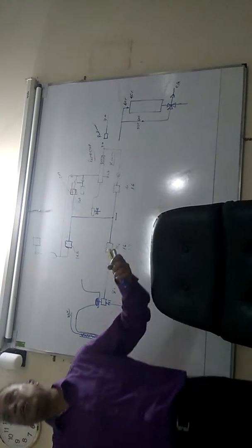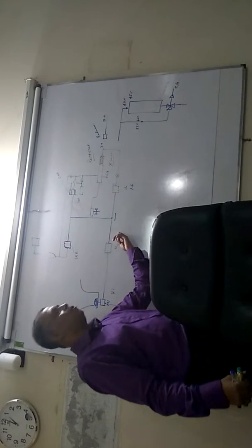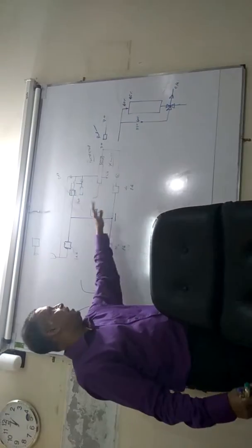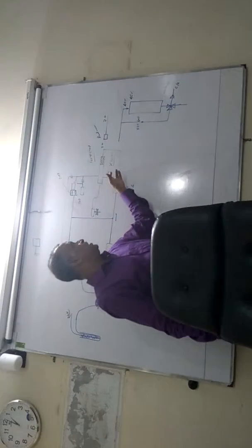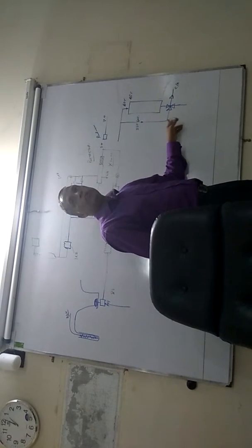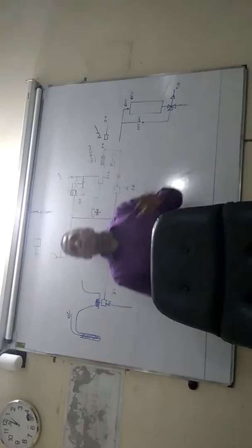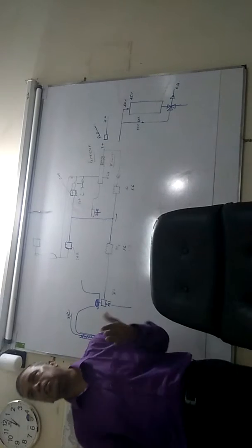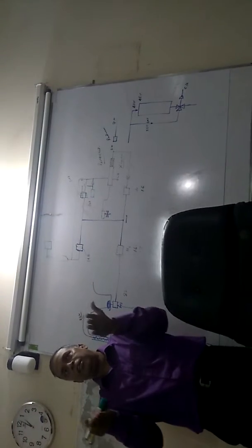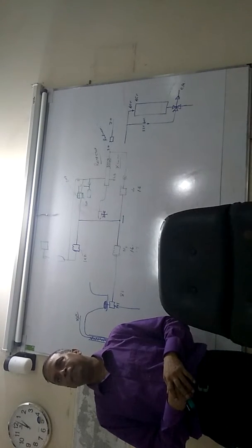Right? A similar way of thinking will be, say this is 78, this pressure reduces, this goes out to the left, the gap between the flapper and nozzle increases, the air bleeding out is increased, the pressure here drops a little, the lesser pressure opens the bypass more, 65% water now bypasses, and 35% water goes to the cooler. Temperature will start to rise because the cooling effect is not as it was before. 79, 80, done. Okay?